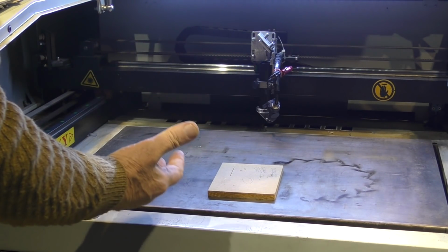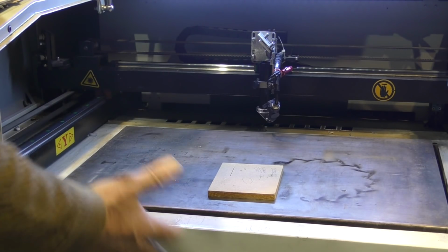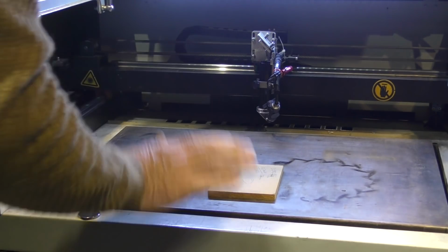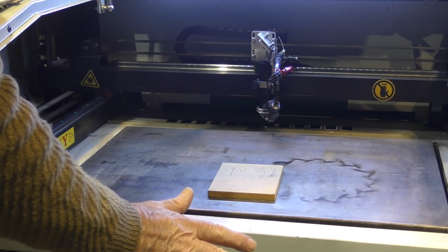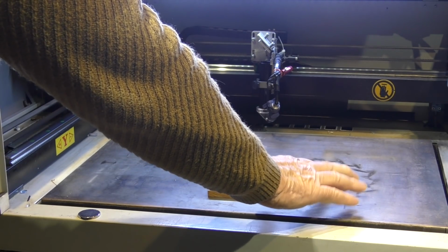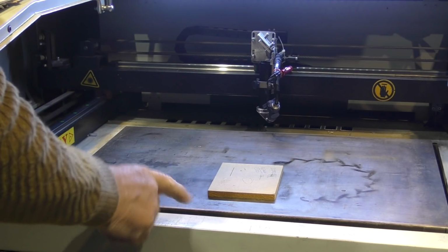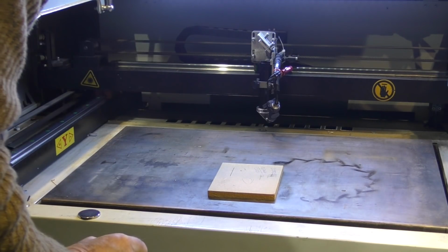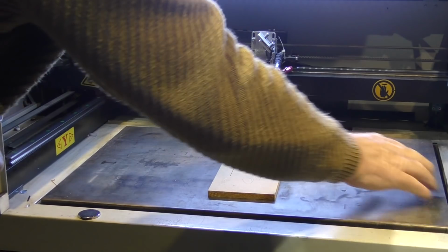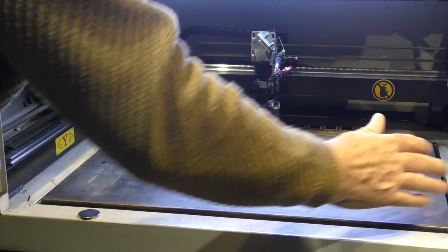What we've really got to do is to manage the airflow through your machine so that it carries the smoke away quickly. Now, I've arranged it on this machine with a closed-in steel bed. Okay, there's little teeny-weeny gaps around the outside, but in essence, what I've got is an extraction duct along the back there, and virtually no places around the edge to extract air from.